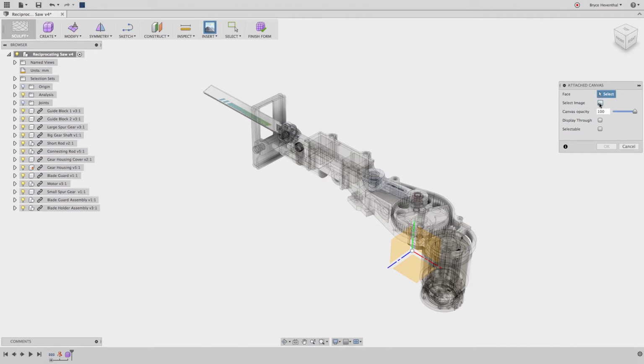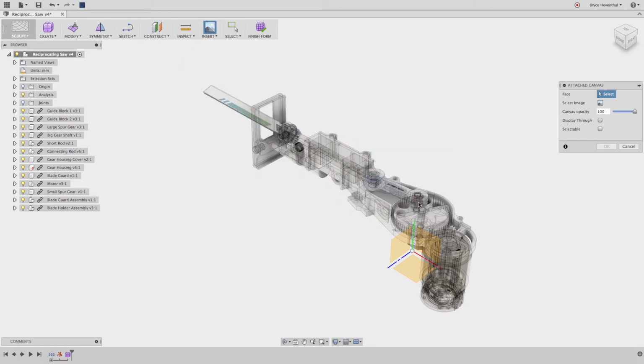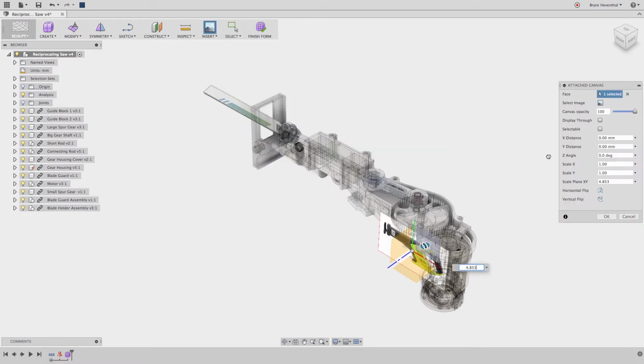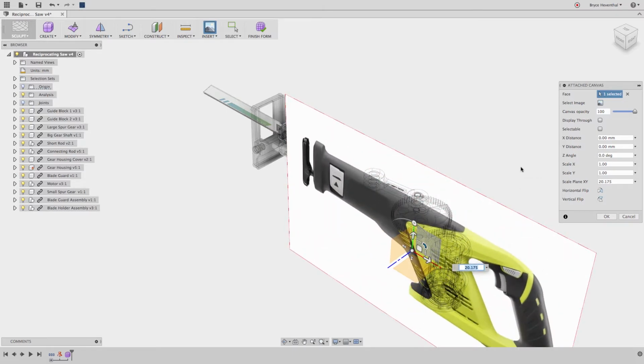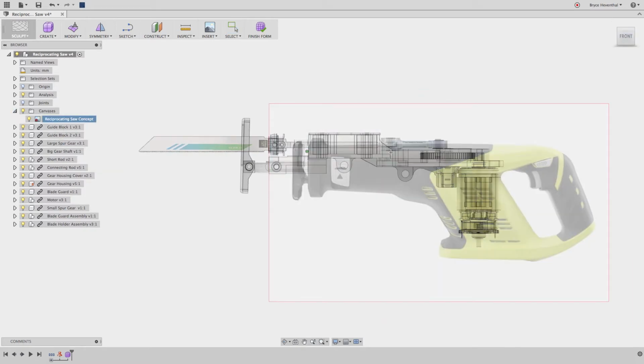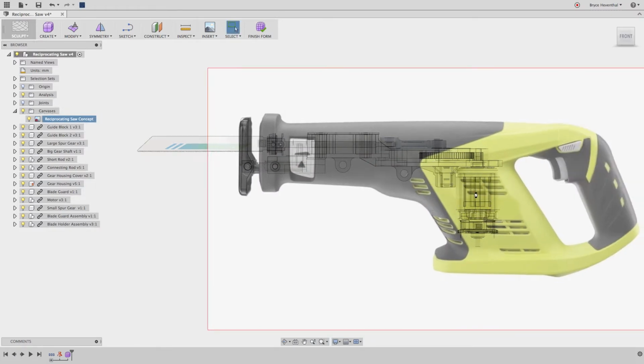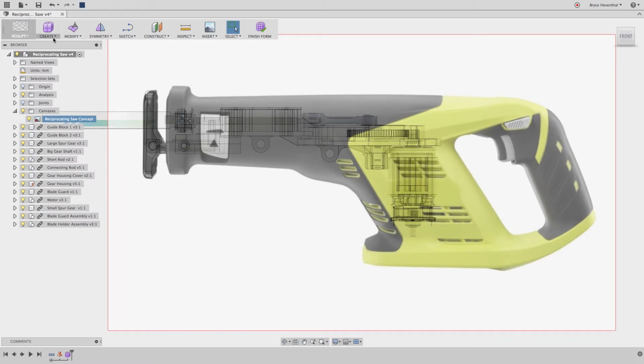One of our industrial designers created a concept sketch in Sketchbook for us to use as a starting point for modeling our plastic housing around. We can resize this image to the appropriate size, but this PNG file used for the image does not have units. I can calibrate this image using a known measurement to better approximate the size of this image. Once the image is in place, we can start creating a T-spline body.